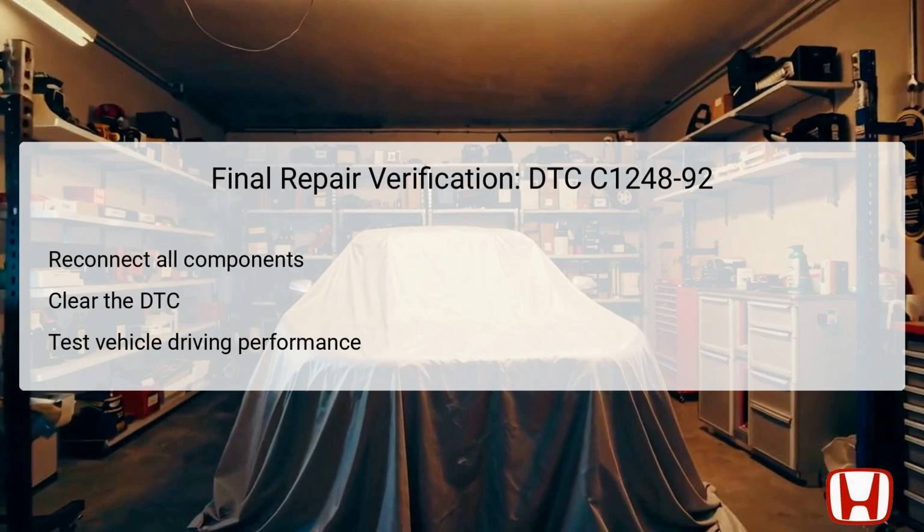Following this, it's important to conduct a road test to confirm the vehicle's driving performance, specifically focusing on the functionality of the electric vacuum pump. This driving evaluation serves as a real-world test to ensure that brake assist and vacuum operations are restored to normal levels. Successful verification confirms the integrity and effectiveness of the repair work performed, ensuring the vehicle is safe and ready for operation.